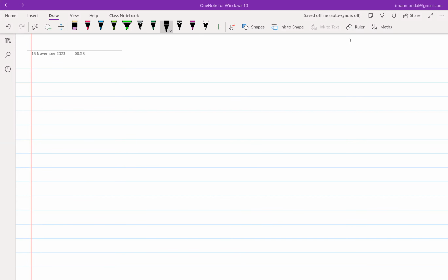So tell me, what was the reason we wanted to go towards a two-stage structure when we had, let's say, a common source amplifier? So let's say instead of putting this resistive load, I'm putting an active load, and this is biased, and so on.